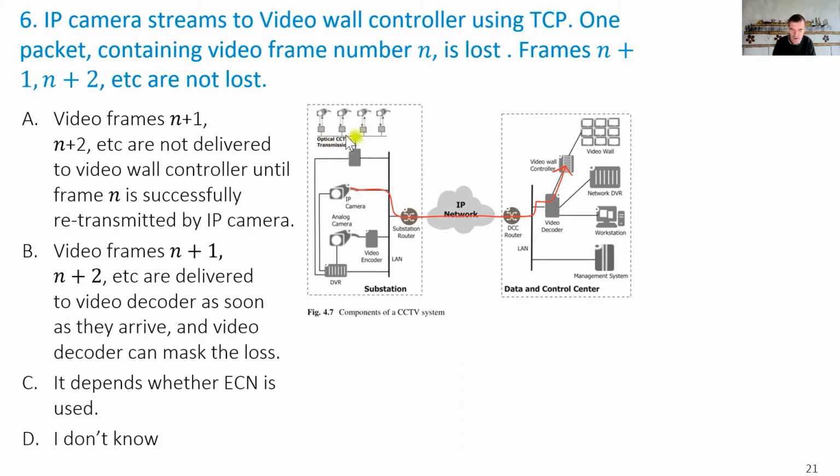So in the unmanned substations, you have cameras, and in the surveillance center, the monitoring center of the utility, you typically have video walls where you see what is happening in all the substations. So these cameras also will go via the communication network of the smart grid to pass the information.